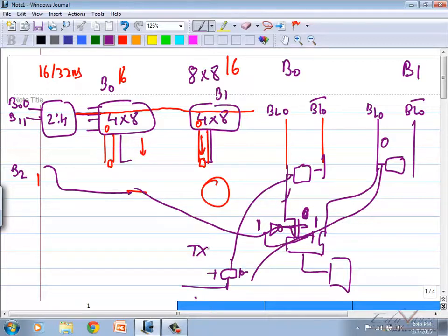When you have a PMOS and an NMOS like this, where their source and drains are shorted, then this is called a transmission gate. If 0 comes here, the output will be 0, thanks to the NMOS, and if 1 is here, the output will be 1, thanks to the PMOS. Everybody following? Yes or no? Any questions?